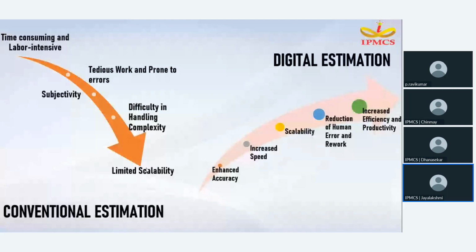When it comes to digital estimation, with software like PlanSwift, we can load the drawing directly into PlanSwift. The blueprints are stored inside the PlanSwift window, in the interface itself. After identifying each element, we can just highlight the element with a mouse click, and it is very easy.